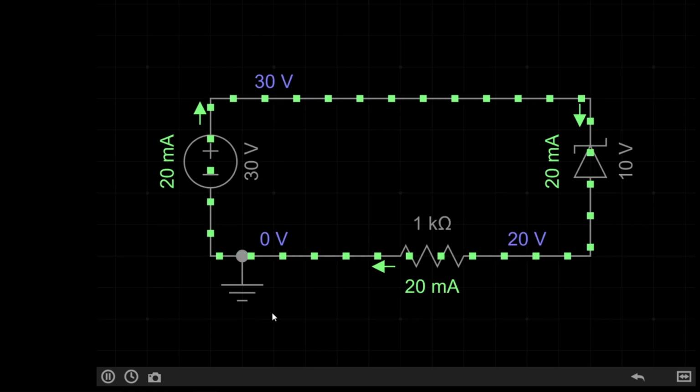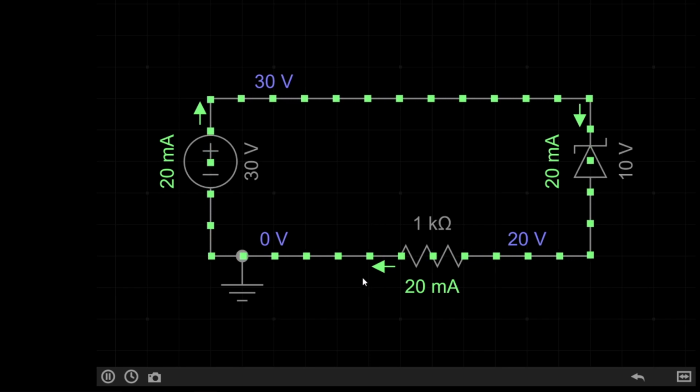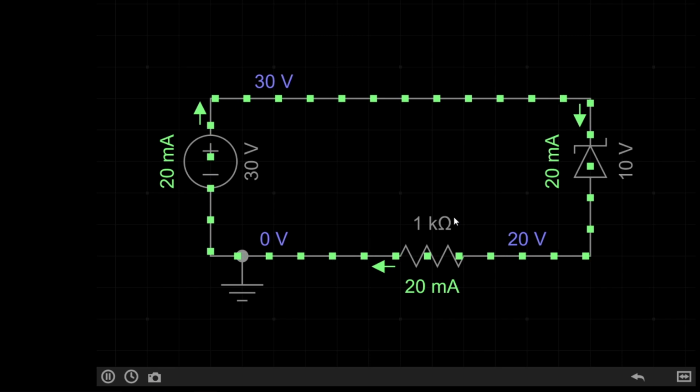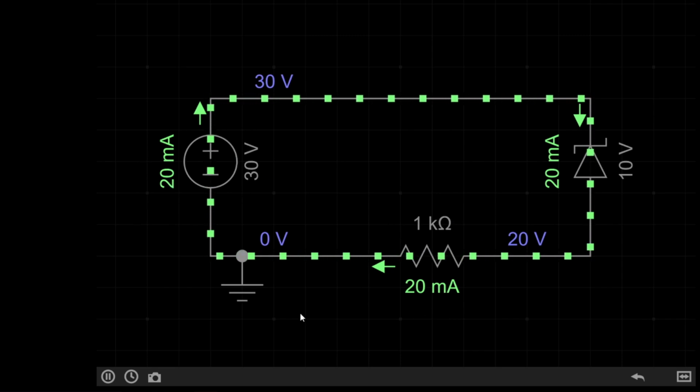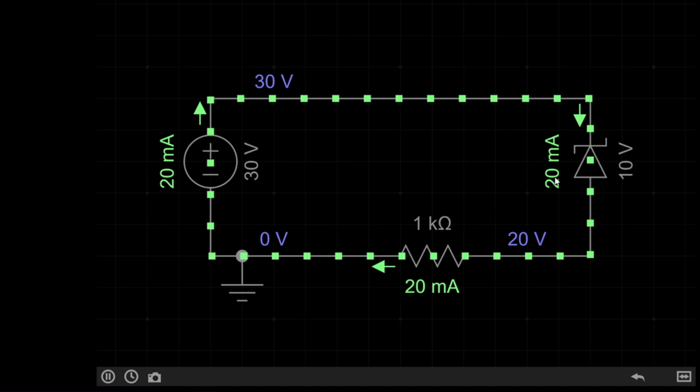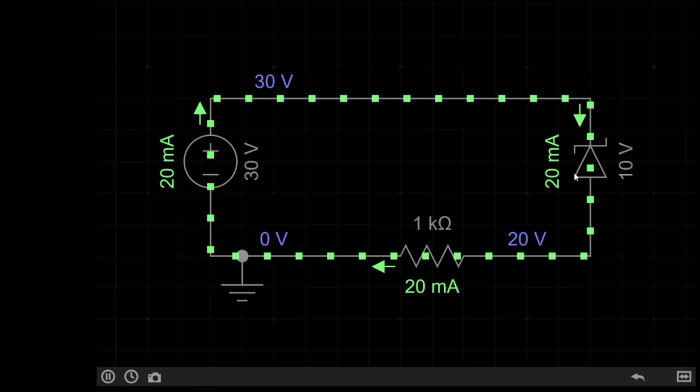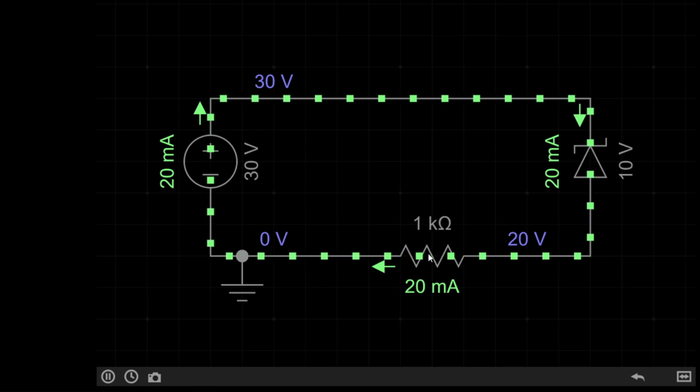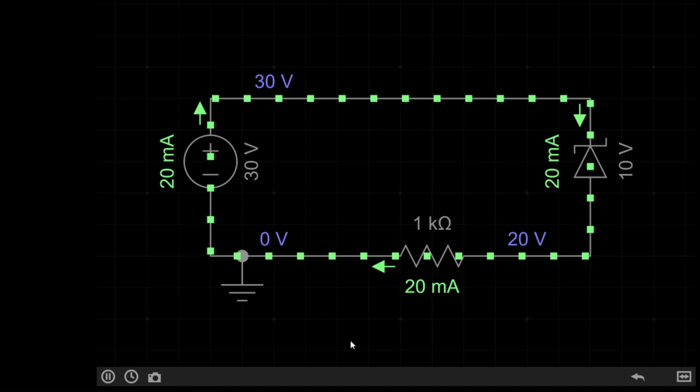In this simulation, let's say we want to supply 20 volts to our circuit. This load is emulating our circuit. However, unfortunately, we only have a 30 volt power supply available. Well, one easy way around this problem is to add a Zener diode that's reverse biased in series with our circuit. As the Zener diode will drop 10 volts, and then we'll have 20 to spare across our circuit. The outcome is that our load now only has to drop 20 volts.